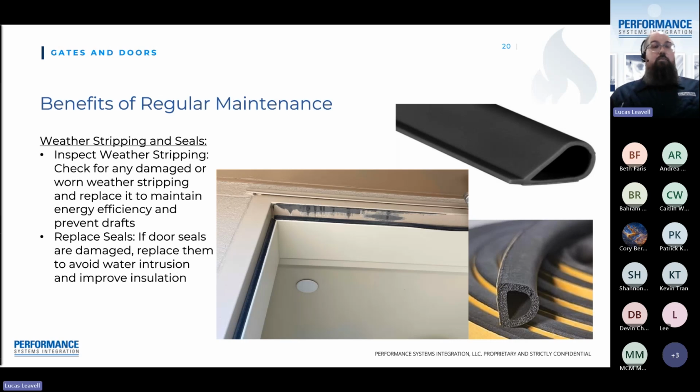Beyond the actual mechanical side of things, the important elements within a door are the barrier it provides between one environment and another. Nowhere is this more important than when it comes to weather stripping and smoke seals. These are often made of a flexible rubber or foam composite that is designed to compress when the door is in its fully closed position. Unfortunately, that does mean that it is now rubbing. It will wear out over time and wear down. These do need to be regularly replaced, especially in doors that are used frequently.